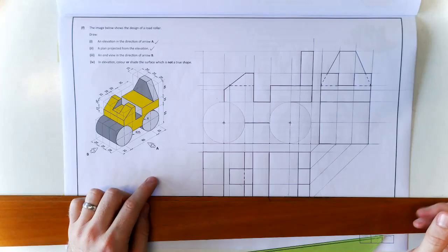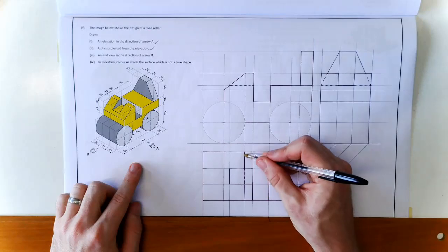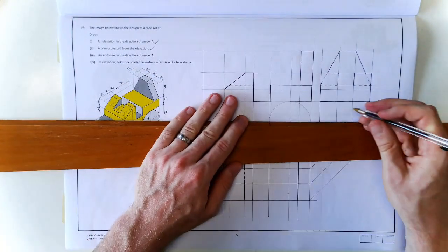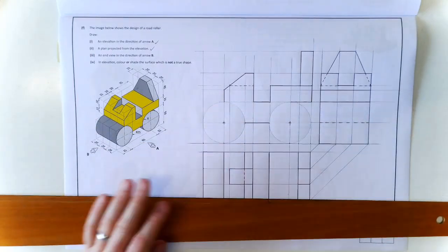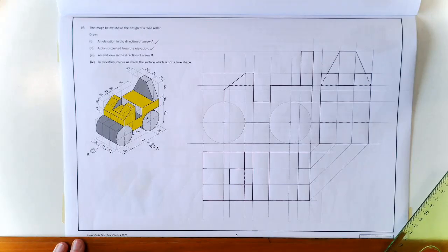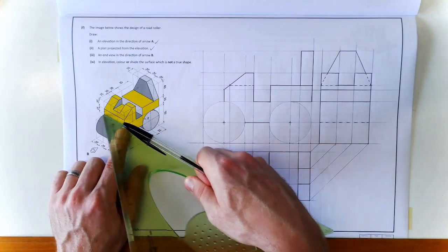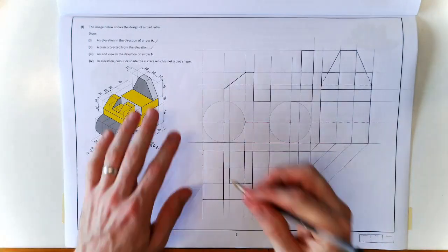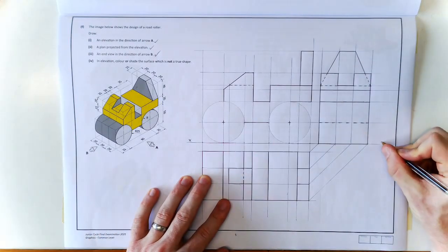I think that's most. Oh, there'll be hidden detail also for that same edge we had here and show down there, running through. It's going to be in the middle there also of our roller. So hidden detail line there also. Okay, the back edge would be hidden detail, but it's in line with that surface. So I think that's all of our hidden detail for our shape. Yeah. So end view completed. And that's our X, Y line.